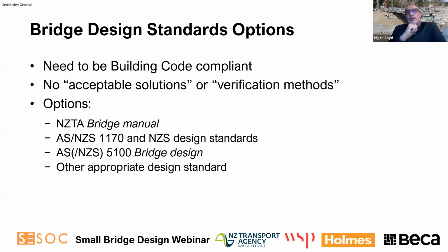And finally, you could find another appropriate design standard. They could be from overseas, say Eurocode or American AASHTO, particularly if you're dealing with certain proprietary products, and it might make it more appropriate for you to use elements of those standards. There are also standards that may be more appropriate for the type of structure that you're looking at. I'm thinking particularly of the outdoor visitor standard that's applicable to New Zealand, and Matt will touch on that briefly shortly.